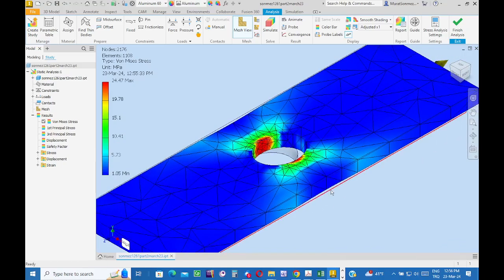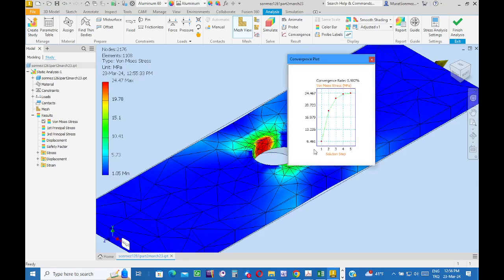Well, it is still the question. We said to repeat the calculation 6 times, decreasing the mesh size in the vicinity of those. Whether the curve reached, say, asymptotically, of course, convergence. Have a look at the convergence graph. Yes, you see that is okay. First running, the stress was 9 megapascal, and then increased in the second repetition, closer to 20 megapascal.